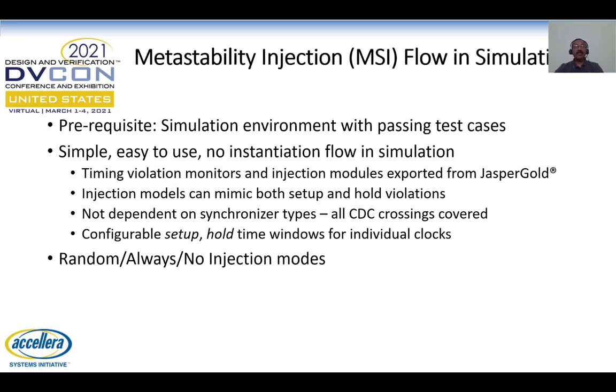JasperGold would generate some timing violation monitors and injection modules, and this can be exported to simulation. These injection modules are complete in nature that they can model both setup and hold violations, and they're not dependent on any synchronizer types. So all CDC crossings are covered when you are doing metastability injection in simulation.